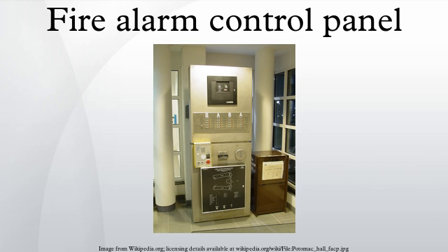When this indicator is lit, power is being provided to the system from the building's electrical system, and not from the backup battery. When an AC power condition changes, the trouble indicator comes on and the AC power indicator goes off, and the screen alerts building personnel of a power failure. If the AC power indicator is lit without any other indicators also lit, then the system is in a normal condition. If no LEDs are lit, there is no power source feeding the panel.